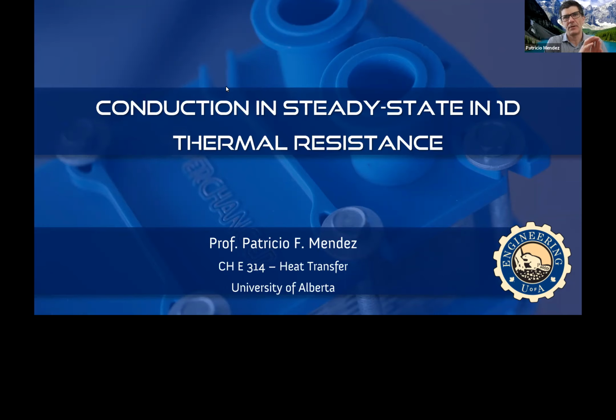If the Peclet number is large, the fluid transfers most of the heat by advection. If the Peclet number is small, most of the heat is transferred by conduction. Then we generalized all that. That is what we just did today. But we didn't solve any problem in particular. We were setting the stage for different types of problems.